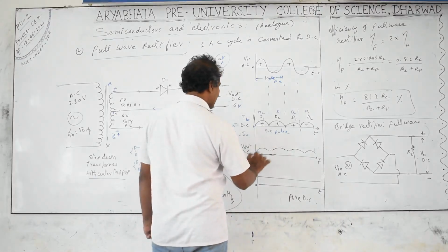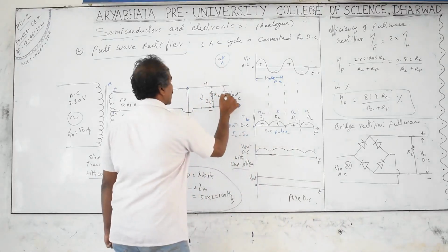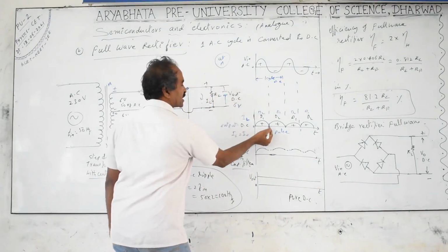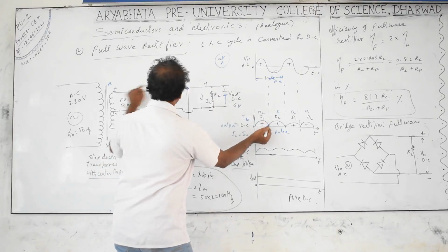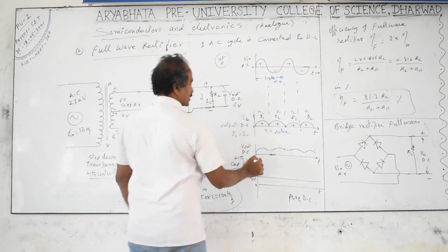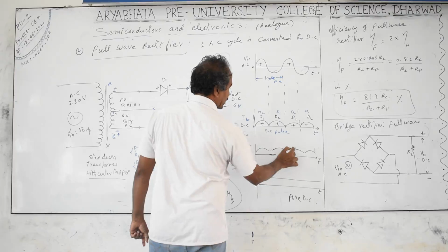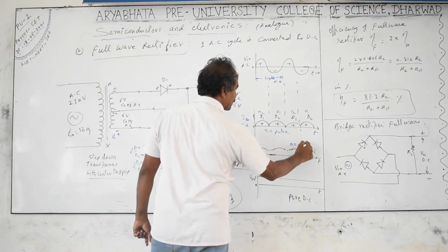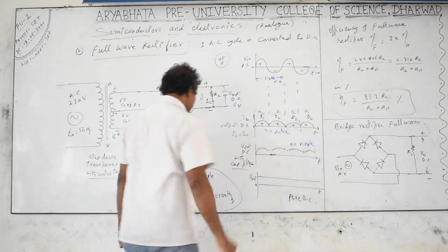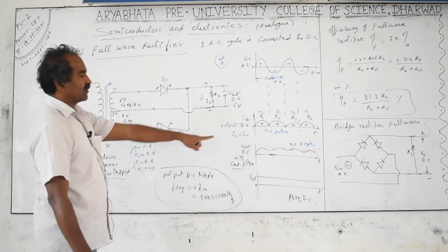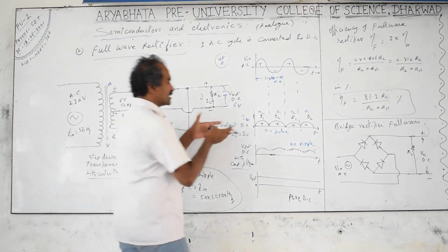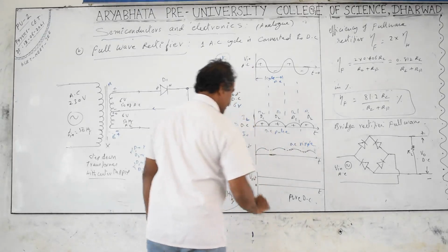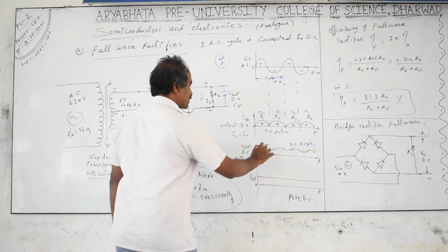If you connect a capacitor filter across the output, the capacitor charges when current is passing. When there is no voltage, that is 0, meaning the voltage is trying to decrease from the input, the capacitor provides the current. Then the output appears as a ripple. It's called DC ripples. Small amplitude waves are called ripples, but they are only DC current. This is called the AC component present in the DC. This is pure DC. But what about the ripple frequency?